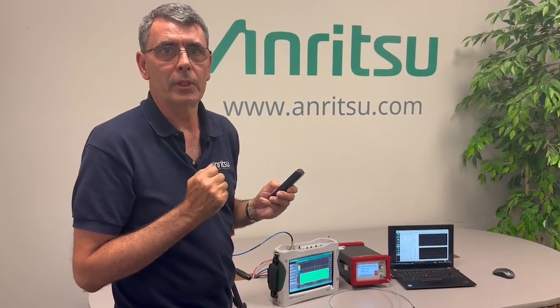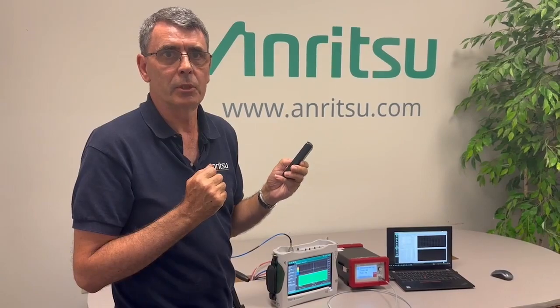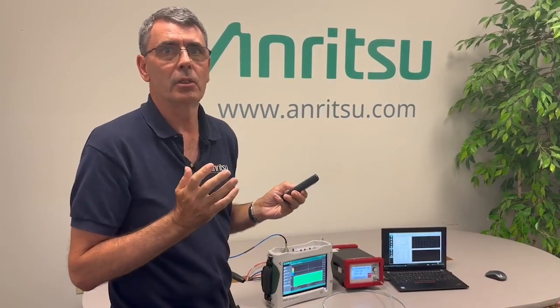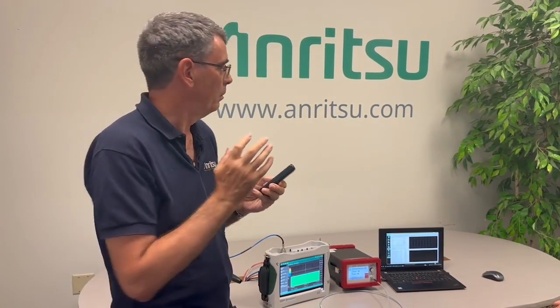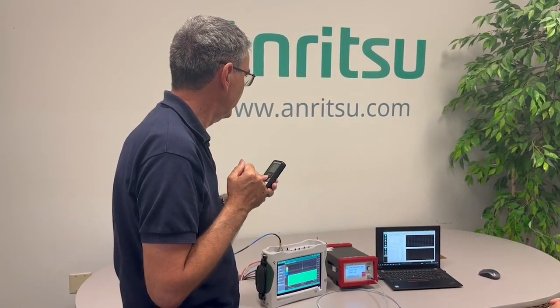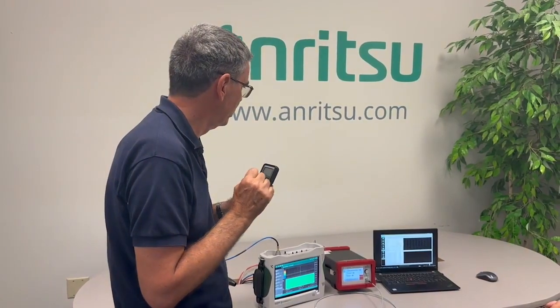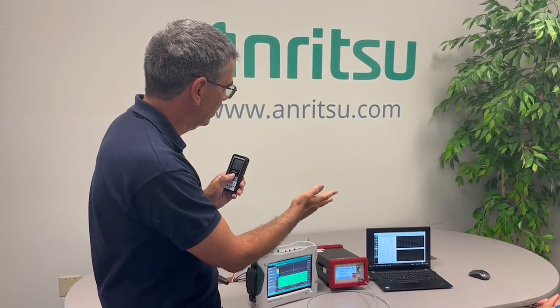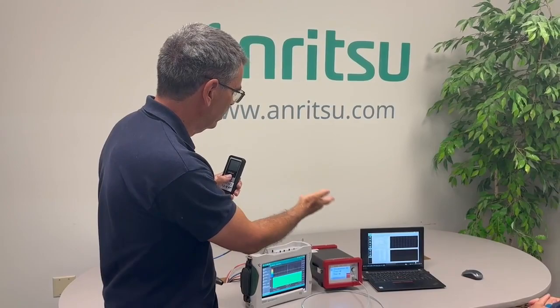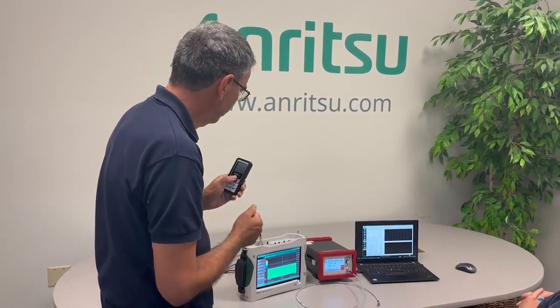What we're going to do now is capture 4 seconds of IQ data from this pocket radar. I've set the analyzer up with a 10 MHz bandwidth. My colleague's going to tell me when to initiate the transmission of the radar. We'll capture 4 seconds, which gives us a few bursts. And then it takes a few tens of seconds to move the IQ data from the instrument back into the PC.